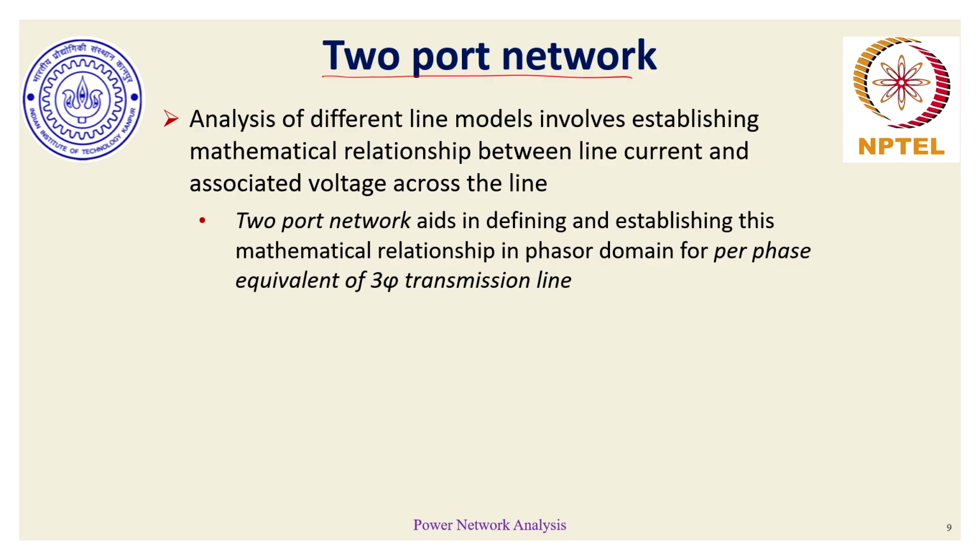They help in defining and establishing analytical expressions, which could be differential equations or algebraic equations in the phasor domain, and they also help in figuring out the per phase equivalent of this three-phase transmission line. Because when we talk about line models and their performance, we need to understand how the line losses are, and how the line is behaving at different operating voltages and different load voltages.